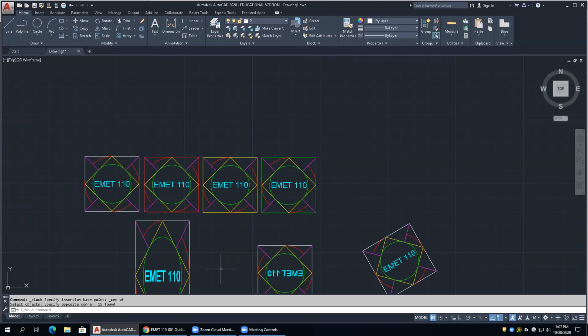How do you fix it? Well, you can't fix it now. So you have to do an undo. You have to undo it and then redefine it. Because once you displace them, they're gone. Okay, they move. Okay. So this was a good question. If you did get your base point in the wrong spot, how do you fix it? I would immediately do an undo, move them back to where they were, and then redefine that block in the proper position. So you need to know where the original base point was.